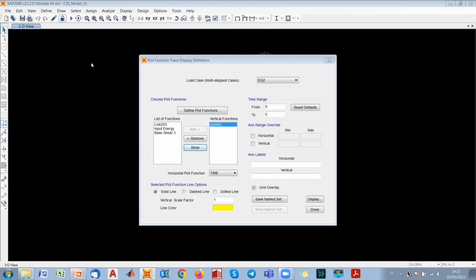And this will be the main result of our definition of the isolation layer. If you remember, our main rule to install isolation devices when we deal with rubber bearings with and without lead core is to pay attention to placing the isolation devices at the edges of the overall system, so that we are maximizing the torsional stiffness of the isolation layer. In this way, the distance between all the devices and the stiffness centroid is the maximum one, and so the stiffness is maximized. So let's have a look, okay, again, a quick one.